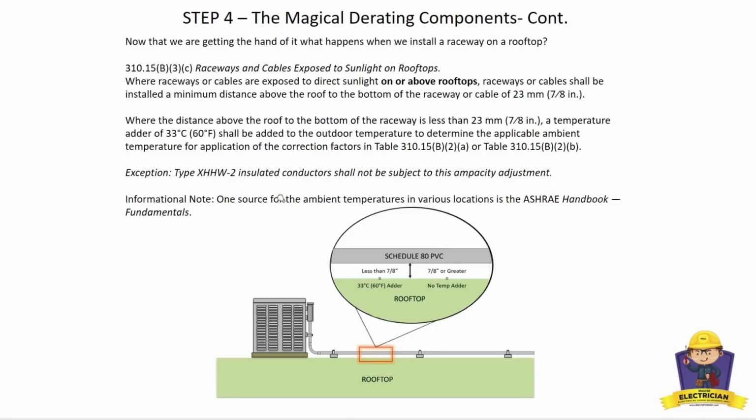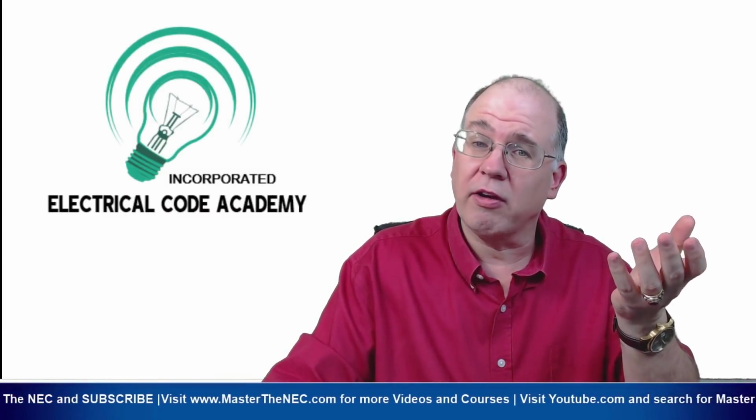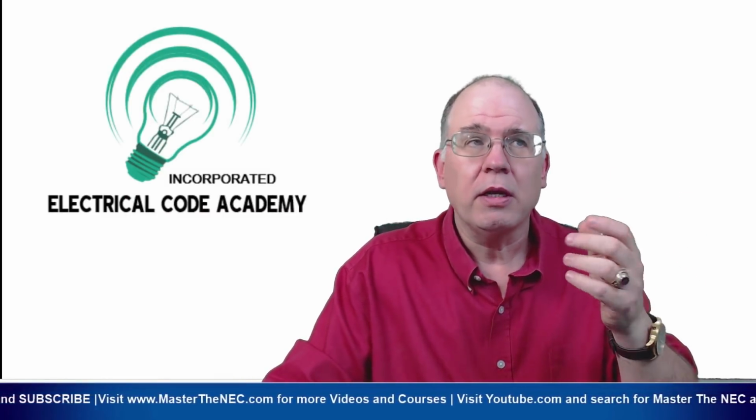Now let's talk about rooftops. 310.15(B)(3)(a) used to be more complex in the 2014 code. It's simplified a little bit here in the 2017 code. Basically, I'm going to paraphrase for you. If you have a raceway on top of a roof, it's subject to direct sunlight, and it is 7/8 of an inch or higher, then you only have to do an ambient correction. Okay, we have to do that anyway. We have to know what the temperature is in the environment, just like we've already learned how to do an ambient correction calculation. So it applies here.